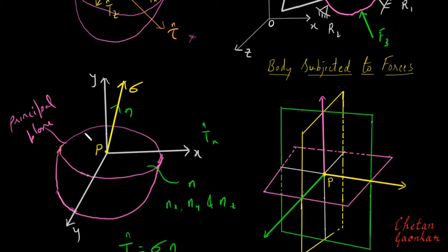For example, if I take this first plane, we know that the magnitude of the principal stress on this plane, what we have got is sigma 1. But what will be its direction cosines? What will be nx, ny, nz values, or what will be the cosine angles between its outward normal and x-axis, y-axis and z-axis? So that is what we will be finding now, right?